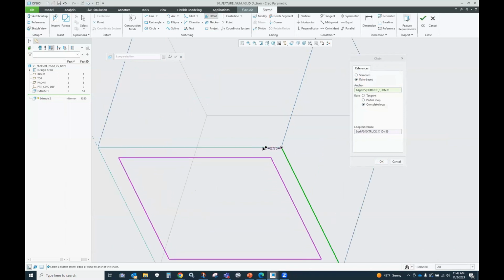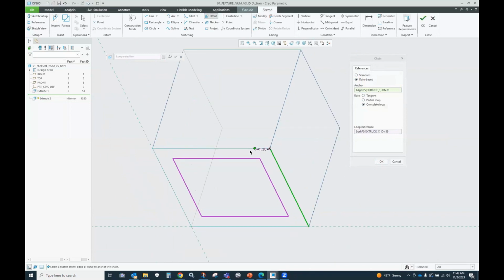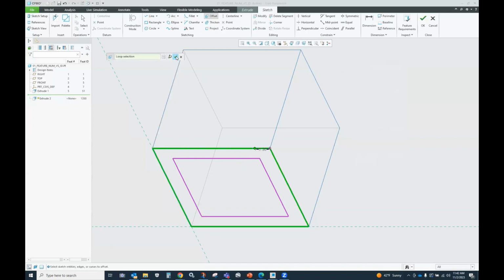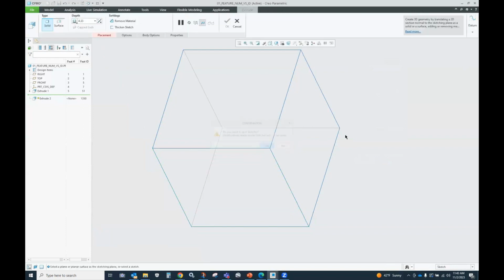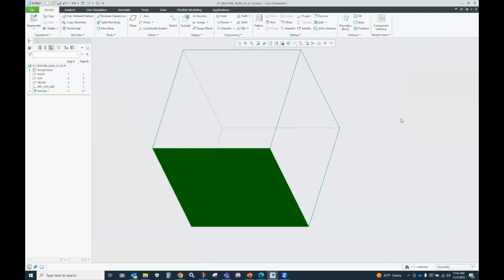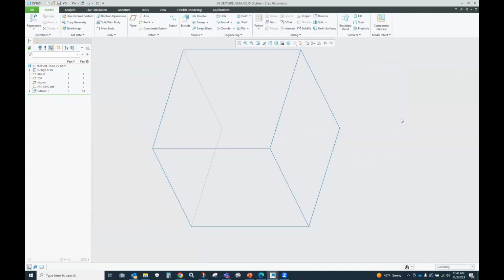So we get a little bit different in how Creo 9 works. I don't know if any of you are on Creo 9, but one of the important things to note is that you do have to use this little checkbox when you're done selecting to create that. So there are these intent selection tools all over the place. You just got to look for them. The most important part is to look for things that might make it more robust for your model, and it's usually an easier pick because I'm not using that control key. So I hope that answered your question.